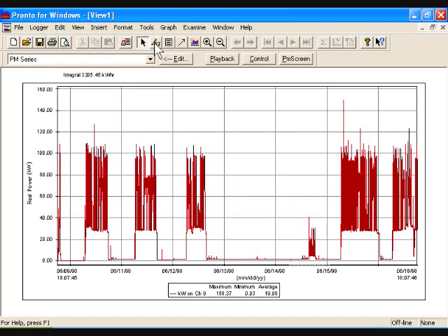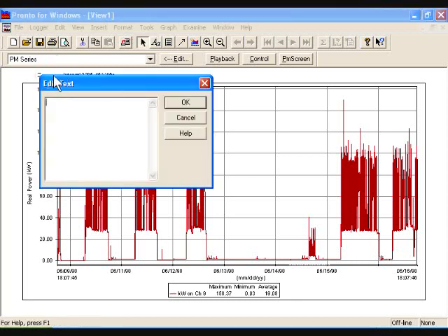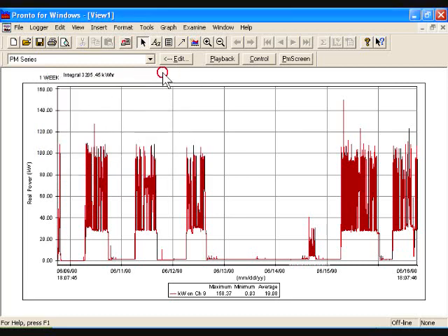And so if you take this, you can move this up at the top, and that's for 1 week. And say we want to put a little text in front of it here to say 1 week. So 1 week, the integral of this entire week of this assembly line is 3,205.45 kilowatt hours. A customer could take that, multiply that times his rate, and see how much it costs him to operate this line for the week.